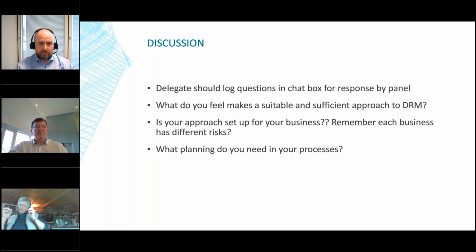But obviously we're trying to look at the bigger picture and what we call the significant CDM issues. I don't like to call them risks because they're benefits and risks at the same time. So they are multifactorial issues, not just what we call one-dimensional risks. So the whole logistics, as you mentioned, the transportation requirements, the size of the panel. On various projects, we have small or low bridges to get the panels onto site, so that constricted the size of our precast panels. Then, as you say, the crane. How many cranes, where are they? Are they capable of taking that size of panel? So all that has to be fed into the design initially.